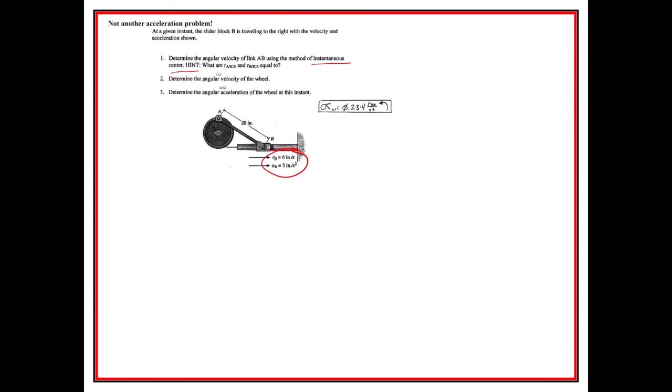It turns out this is one of those trick questions. I'll draw it on the board, but if we want to find the instantaneous center of rotation, we take the line perpendicular to the velocity at B, and then the line perpendicular at A. It's really, really easy to fall into this trap.